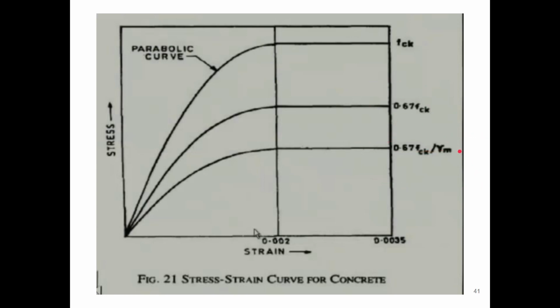So will the material be as per predicted? Definitely it will not be. It will not be ideal, but the design is ideal, right? So in order to take into account the uncertainty in material, we again divide by 1.5. So we divide by 1.5 two times: one to take into account the uncertainty in site conditions, and the other 1.5 in order to take into account the uncertainty in material condition.